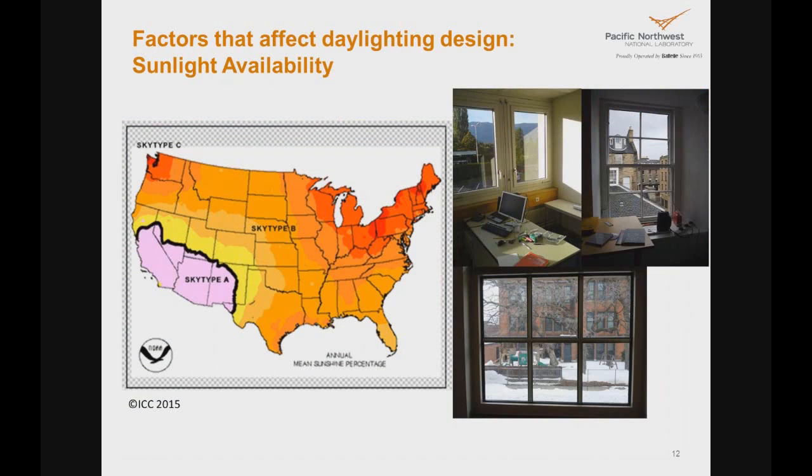So when a space is designed for daylighting, there are several factors involved. Generally, we start by asking how much light is needed in that space. So that refers to that previous chart. Daylighting cannot generally supply very high light levels needed for certain tasks, such as working with jewelry. But daylighting can generally supply ambient levels required for moderate office work, just typing, reading, writing, and so on.